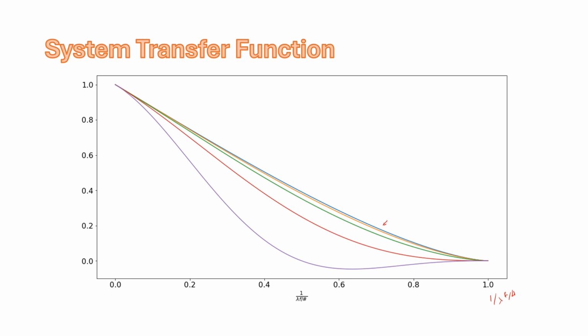The red curve corresponds to sampling with a sampling period of lambda f number, which is twice the Nyquist period, and then the purple curve is 4 times the Nyquist period, sampling with a period of 2 lambda f number. And here you're seeing the spatial frequency response drop as we increase our sampling period, and the effect of pixel modulation becomes more pronounced. But it's important to also remember that as we decrease our sampling rate, the Nyquist frequency also changes, and so we'll see impact from aliasing as well.